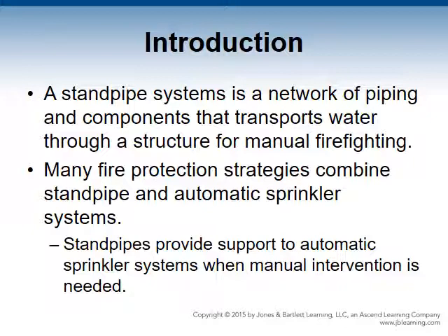Fire protection design strategies combine standpipes and automatic sprinkler systems. The strategies apply to retrofitting an old system or installing a new sprinkler system. The standpipe doubles as a water supply riser for the sprinkler system. Automatic sprinkler systems are usually very reliable, but in cases where manual intervention is required, the standpipe system provides the support.